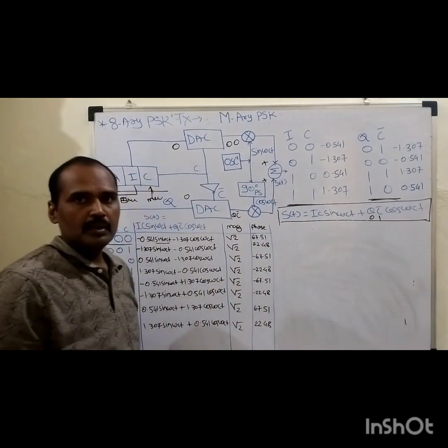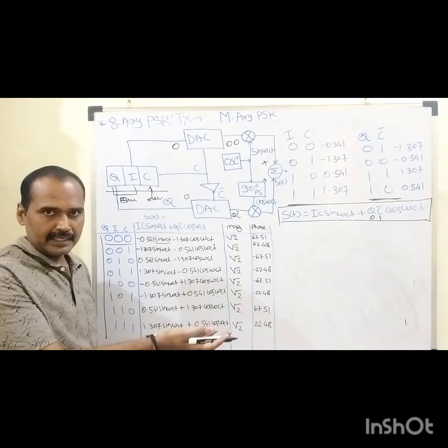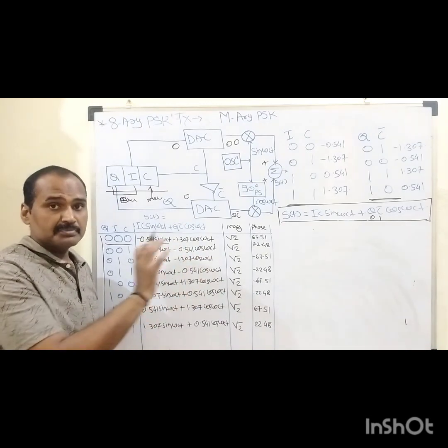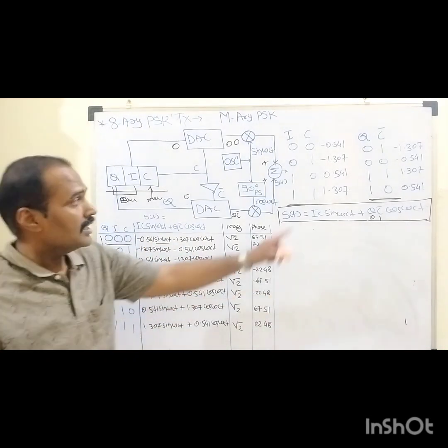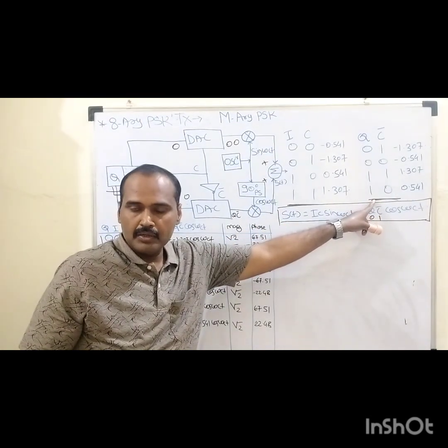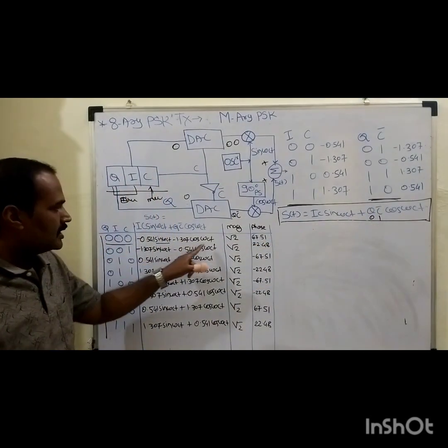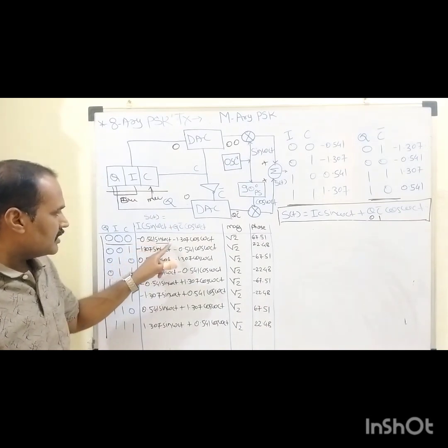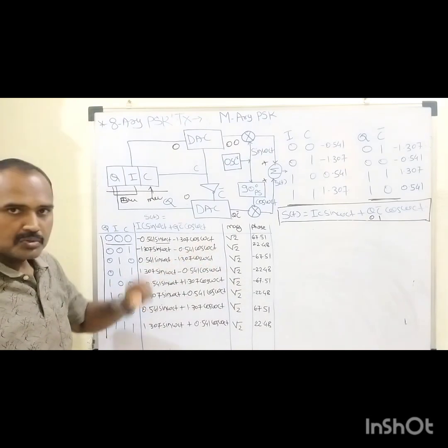So in order to draw the constellation diagram, first of all we need to represent how the modulating symbol sequence is expressed with the help of these 8 different symbols, by taking into account these two assigned tables with the help of the 2 to 4 level code converter, right? So in this way the first symbol is represented: minus 0.541 sin omega ct minus 1.307 cos omega ct.